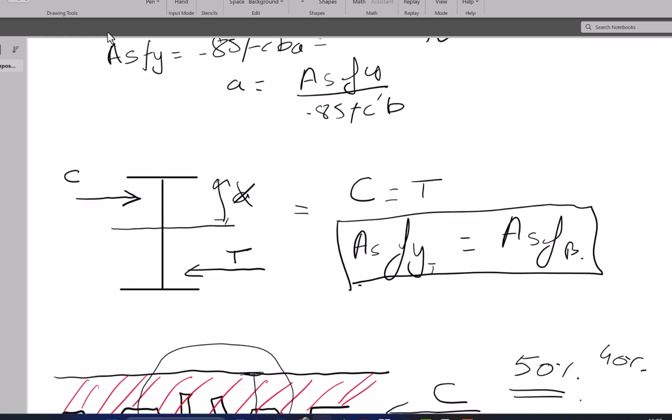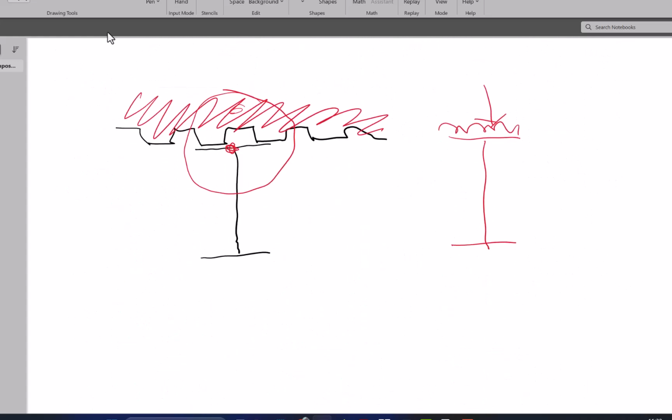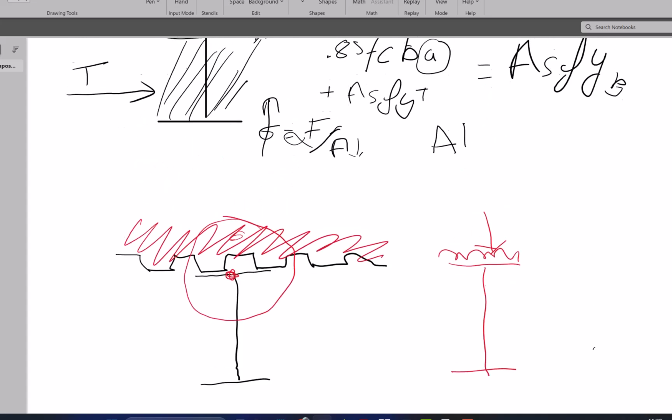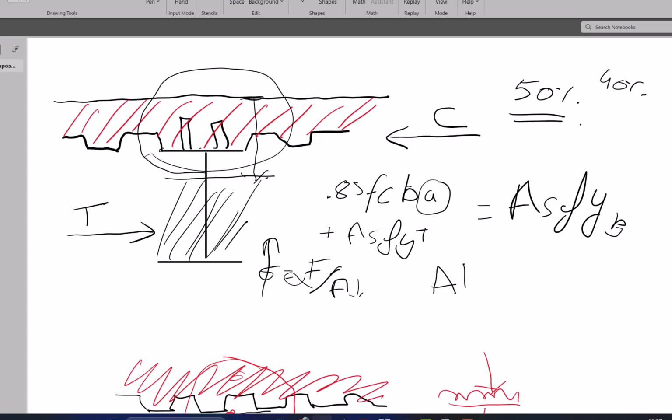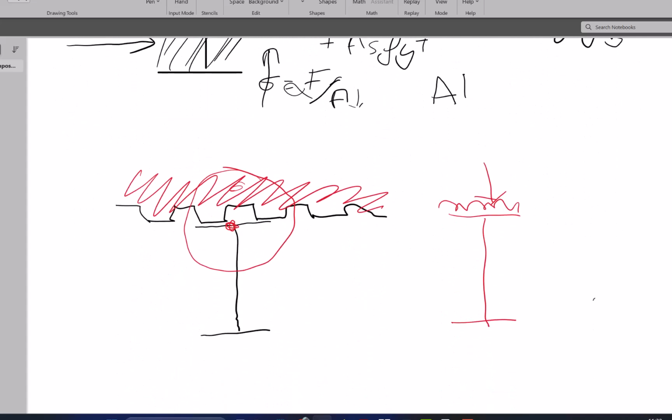If it's a composite beam, obviously when concrete is participating in the stress and you have a higher area in tension, then this becomes economical. We'll see in a bit how economical this is, and this scenario is uneconomical. This is not a composite beam.